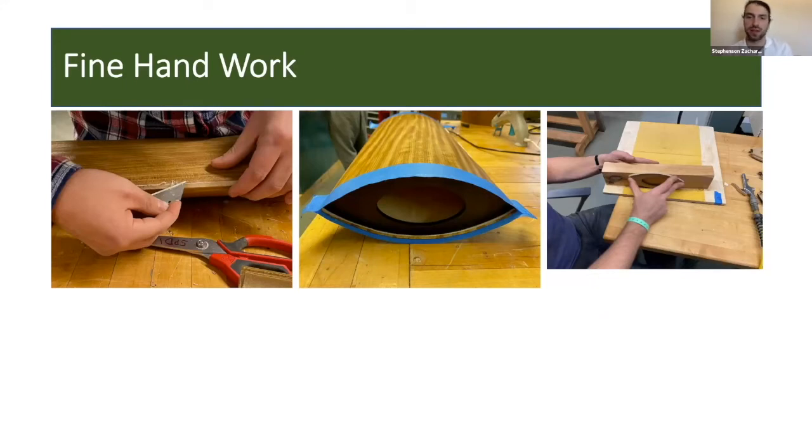Another thing, like Aiden was just talking about, is that after the lamp came out of the press jig, we had to cut off the excess veneer on the top and the bottom, in order to be able to fit it into the sanding jig. And we had debated sanding it off, but we were afraid that if we took a sander to a piece that thin, it would cause cracks and splits along the entire length of the lamp.